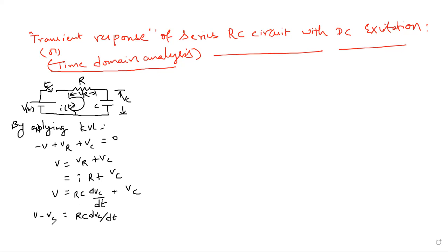And how can we turn this? Right, dVc by V minus Vc equals the reciprocal 1 by RC multiplied with dt. Shall I write like this? The cross multiplication: V minus Vc on the right hand side and RC dt on the left. I just replaced that. Done up to this, any doubts? Just focus for 10 minutes and we will finish. Up to this, are there any doubts? No, sir.